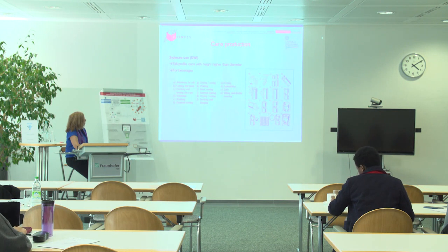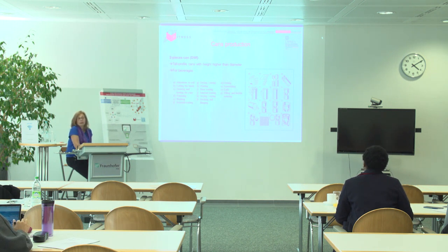While when we want to do a beverage can, we start with a certain thickness, but we increase the size of the can by ironing the metal. So the can starts to be thinner and thinner and thinner. So beverage cans are typically very thin, while the food cans are not so thin, are thicker. So the process is different, because different types of processes are used.